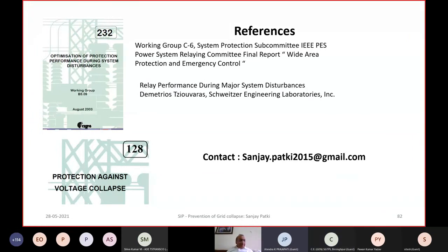Sir, I want to ask one question. If any line trips in a zone and its distance relay shows the fault location, some kilometers, and if there are two distance relays, the distances are slightly different between both relays. So what should be the exact starting position of the fault location? Should it start from zone or current or any DF start like that, so that the fault kilometer should be the same in both relays?